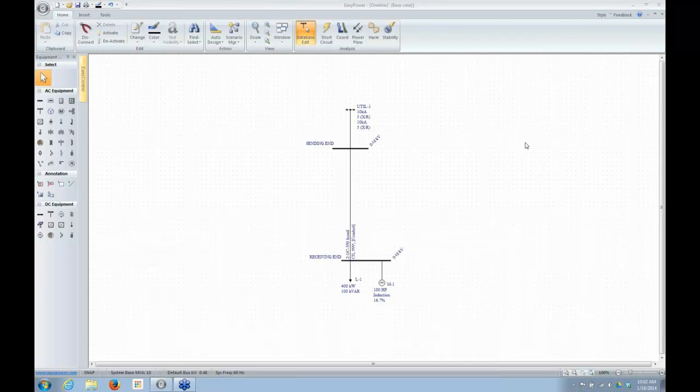The basic issue with power flow is this: if I look at this simple system here on the screen, you'll see I have a source, what I'm calling the sending end, and what I'm calling the receiving end. The basic power flow problem is that for whatever load I have down here, in general, the amount of current or power drawn by this load is a function of the voltage that it sees where it's connected at the receiving end.